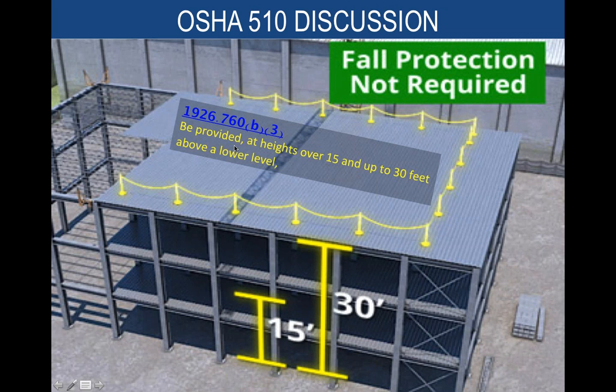Okay. We have to keep out from under the raised loads unless we have duties that are going to be requiring us to be there, like a rigger or something like that, or somebody receiving a load. We also have to keep out from under raised loads, like we're talking about. Never ride a load or crane hook. Okay, we can't ever ride a load or a crane hook at all.